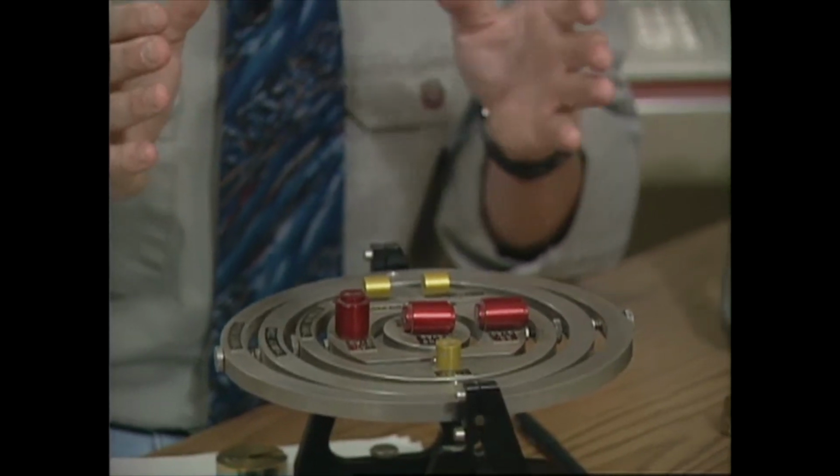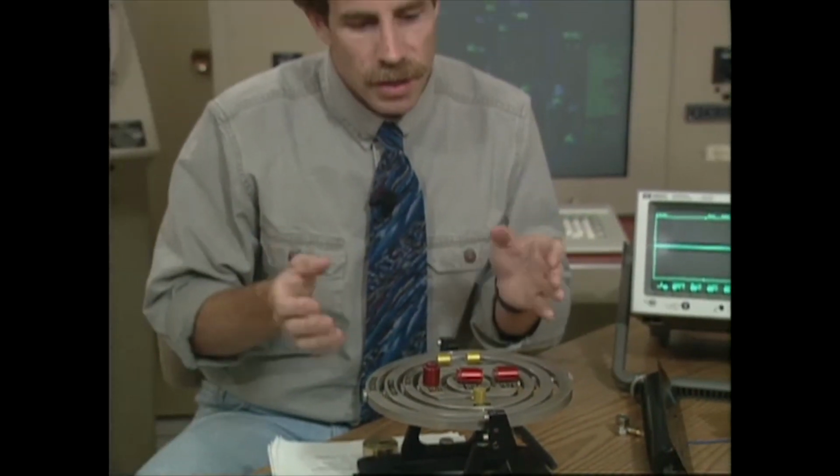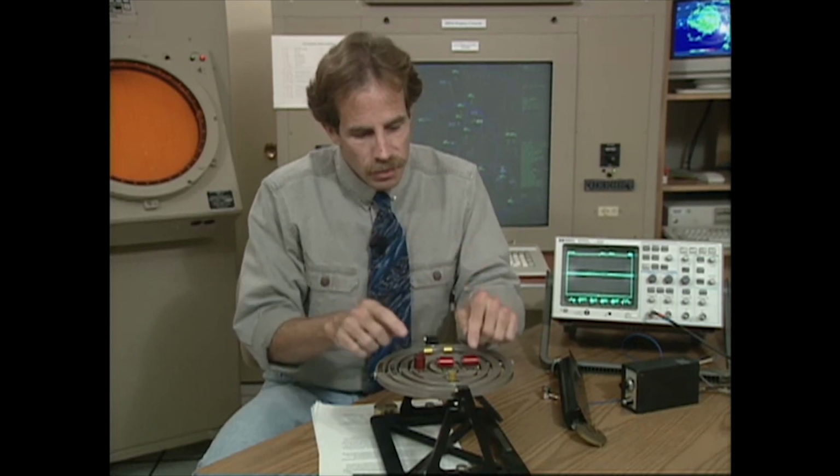And this is very desirable for applications such as submarines and some flight vehicles. And units like this are called inertial navigation systems. Now, it isn't sufficient to just measure the acceleration because you also have to be able to know which direction you were going. So these three red devices here are gyroscopes. And what they do is they measure any rotations that the vehicle has undergone.